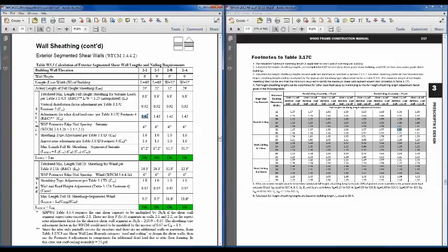But again, if you were to assume a whole additional story up there, your wall length requirements that you pull out of the table here, instead of 8.8, it's probably going to be twice that. It's probably going to be 16 feet required. We're going to end up bumping it up by about a 50% increase.